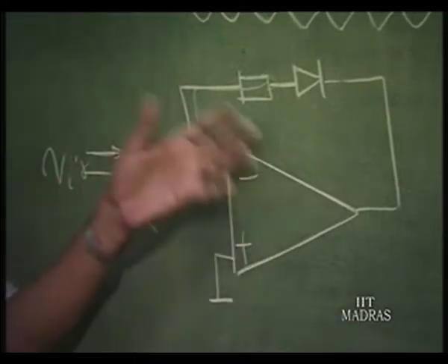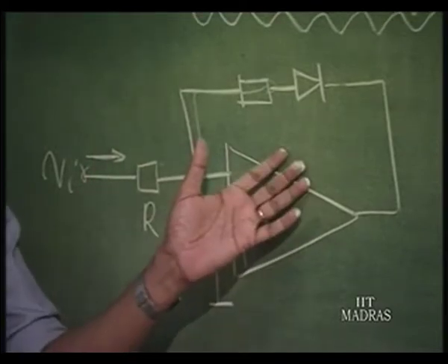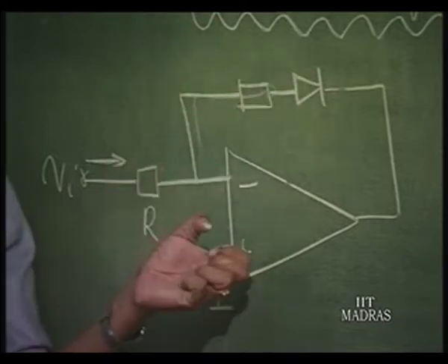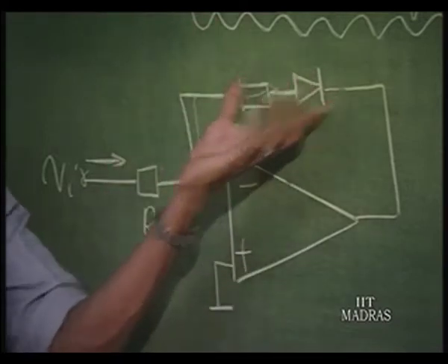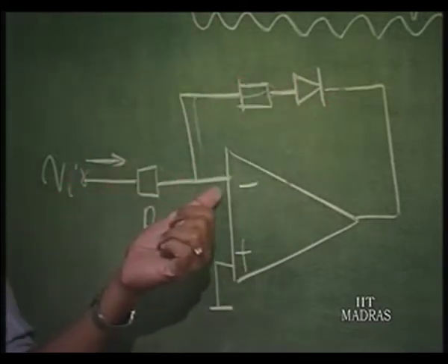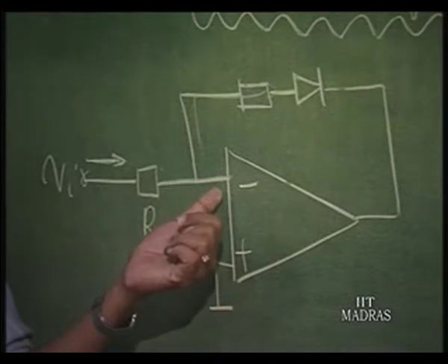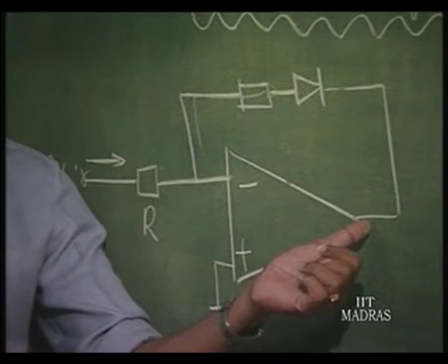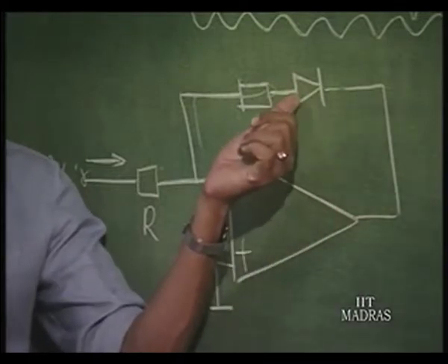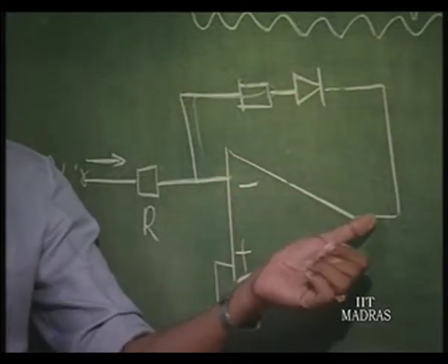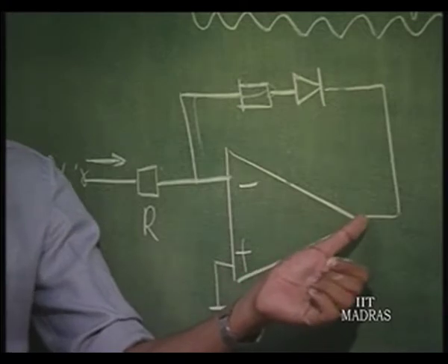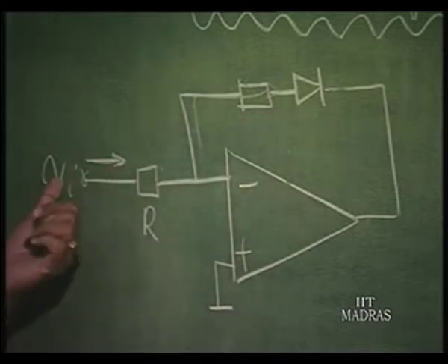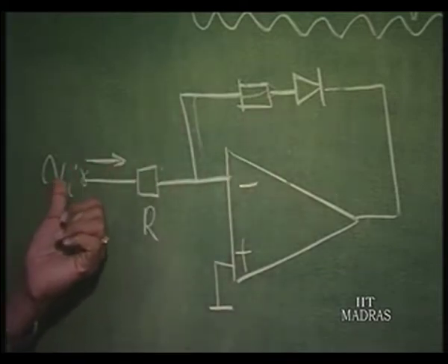So, if the op amp does not get negative feedback, then the open loop causes this voltage to appear here, even if it is a small positive value, microvolts, this will try to go to negative saturation and the diode will jump to V gamma. So, this is what is happening. This op amp will try to make the diode conduct even if the voltage is a small positive.